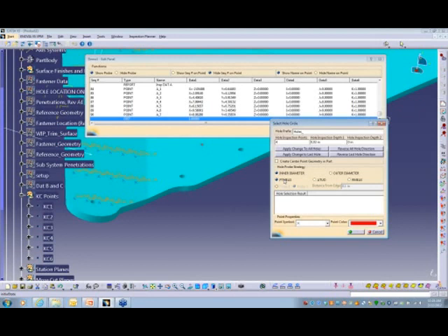Or we can do an R measure hole which probes the face of the surface and then adjusts down to the exact depth. So we have program mode, auto mode, or vector mode, or R measure. Different people call it different things, but there's 3 strategies in probing a hole, and then we can do inside or outside diameter. So for this case, we'll do an inner diameter, and we'll set the 4 hit points.